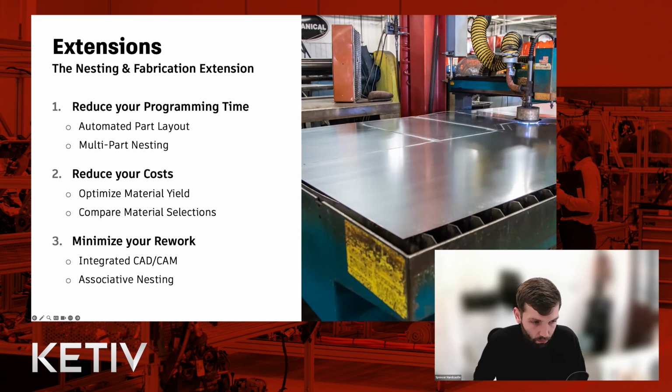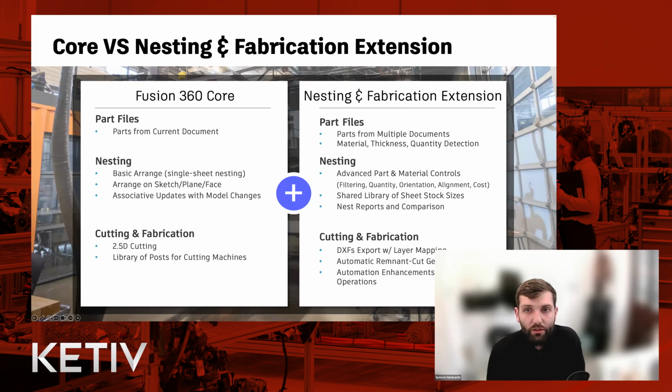Okay. Now there's one thing that we should talk about before we dive into these tips and tricks, and that is that Fusion does have some, in quotes, nesting capabilities in the core offering. It's called arrange. And what arrange allows you to do is nest or arrange parts from the current document, the document that you have open right now. And that's where that functionality ends. It allows you to arrange on a single sheet. And effectively what it is is pick and click, right? You select the components you want to arrange, you select the area or the face or the sketch that you want to arrange it within, and away it goes.